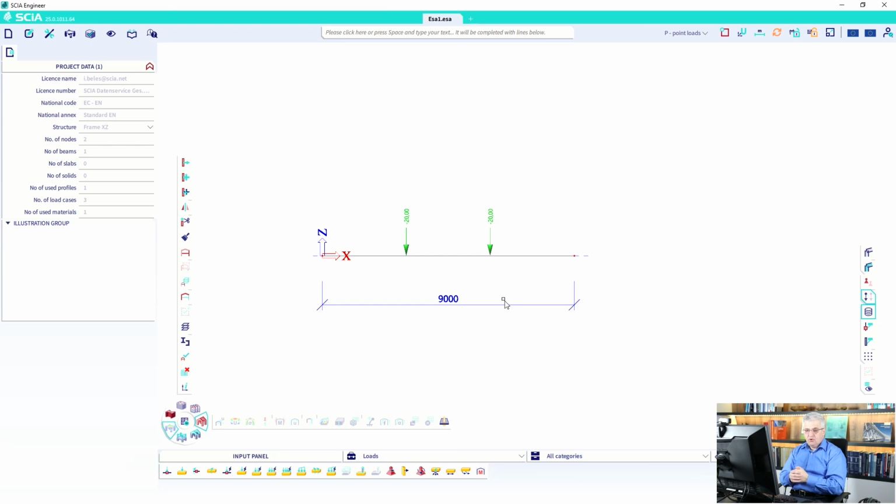Why? Because, for example, if you have a building, usually you have one combination of masses. You have one situation for which you calculate the earthquake analysis. You have the self-weight, you have permanent loads, and with Psi2 or Psi-E, you have the variable loads. But you can also have, for example, a swimming pool, or you can calculate, for example, silos or bunkers. They can be full or empty or half full.